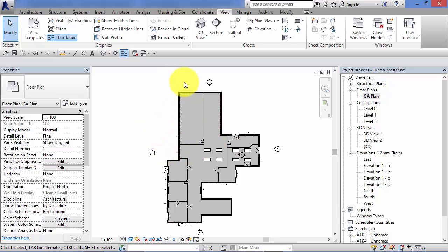You can think of Revit elevations as basically cameras pointing at the model. This means that the elevation is always live and is always synchronized with the floor plans. So if, for example, as we develop our scheme, we move the window positions or add some doors in, the corresponding elevations will always be a true representation of that design. So those windows and doors will move or be added accordingly.